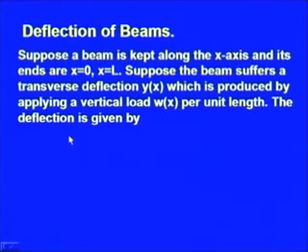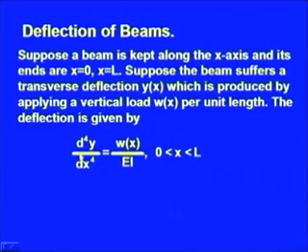Then the deflection is given by this differential equation: d⁴y/dx⁴ equal to w(x) over EI, for x varying from 0 to L.